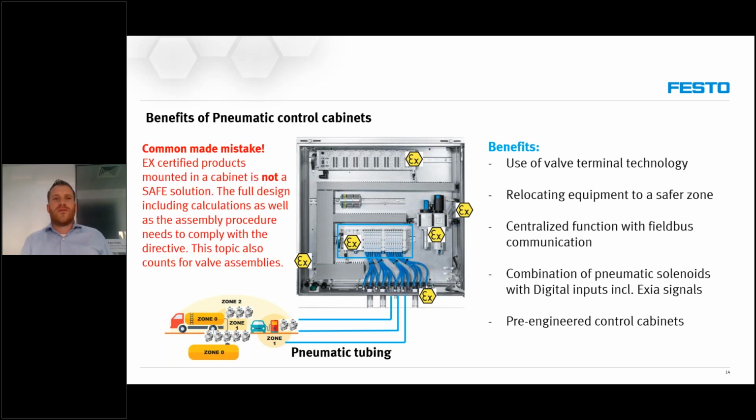Unfortunately, and this is where we see a common mistake, in the market we see a lot of cases where individual components, ATEX certified or not, are installed in the full design, and then the calculations are being missed and there is no further certification as well as documentation supplied with this equipment. So in that case, people believe they have a certain safety within their plant, which actually is not.